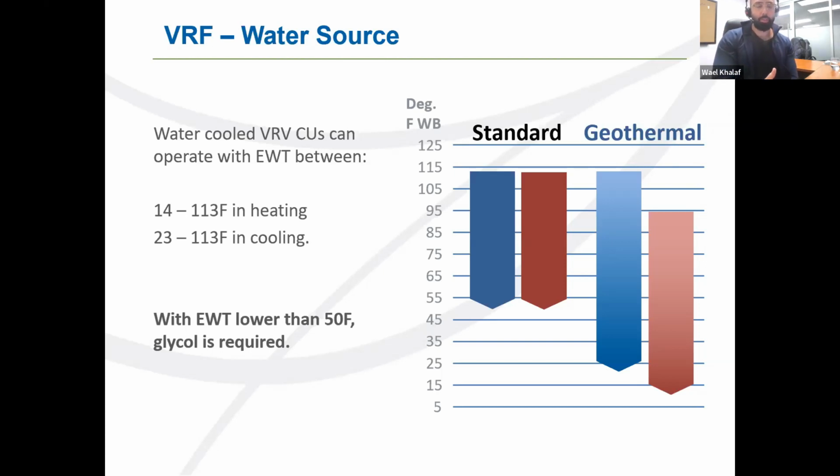What changes really between both heat pumps? It's very similar. Some items are changed and some accessories are added, like added insulation, because the water entering the heat pump will come back really cold. So we want to avoid ambient air condensing on the evaporator heat exchanger inside the heat pump.